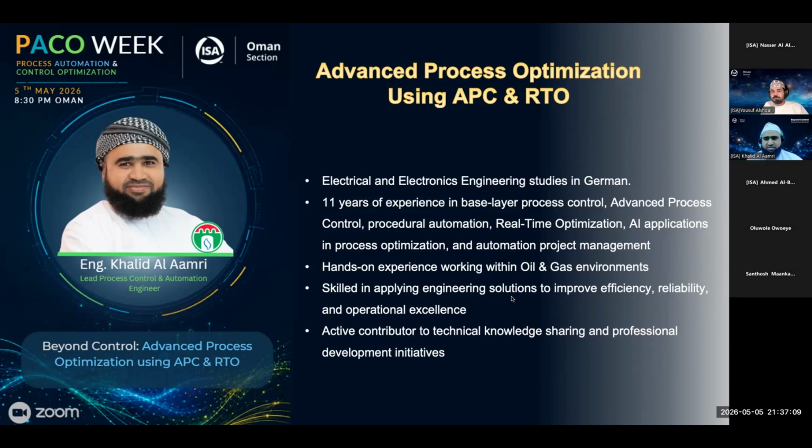The initial things I remember from my days is that if your operator has his hands very busy playing with the process, you know that you need to have an advanced process control. If your dead time is large and the operator needs to wait a very long time to see the response in the process, go and implement the advanced process control.